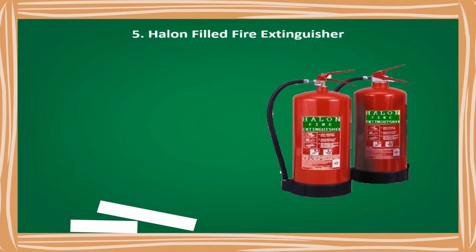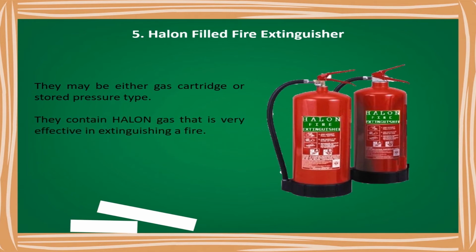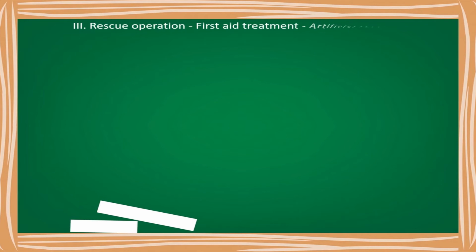Halon filled fire extinguisher. They may be either gas cartridge or stored pressure type. They contain halon gas that is very effective in extinguishing a fire. Most suitable for fire involving liquids, electrical equipments. Rescue operation, first aid treatment, artificial respiration.